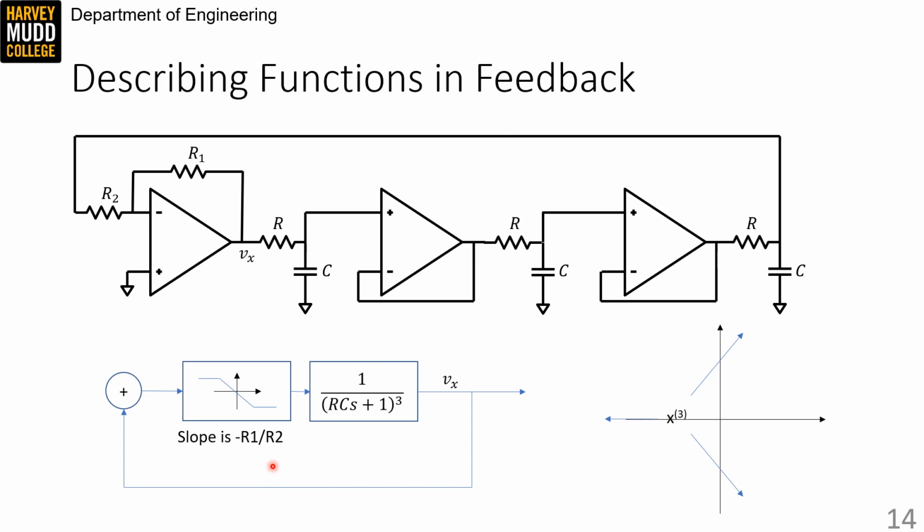And that's interesting because this describing function that replaces this nonlinearity is kind of in the position that a gain term would be in a root locus analysis. Like if you were trying to find the root locus of these three poles, you'd put just a gain of k here and then vary the value of k. So we know that when our input amplitude is small, our describing function is going to be large, and that will mean that we'll move far out on the root locus of this diagram, so our poles will shoot way off into the right half plane when we have a small input amplitude.